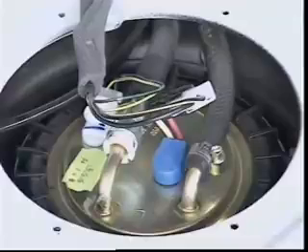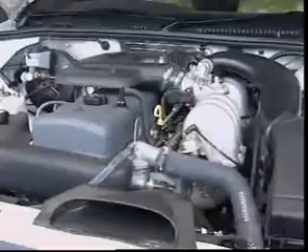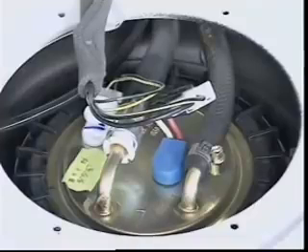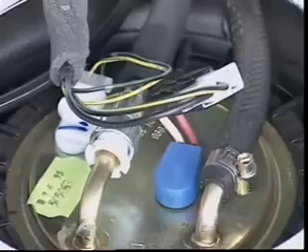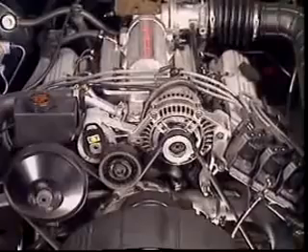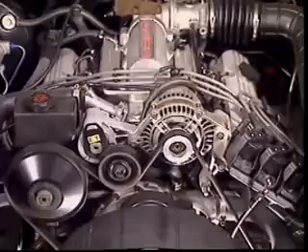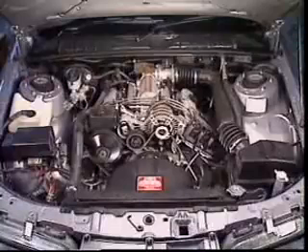The ECU can control the fuel pump. For safety reasons, when the ignition is turned on and the engine is stationary, the fuel pump operates for a few seconds only, enough to prime the engine for starting. It starts again during cranking and when the engine is running above a specified minimum number of revolutions per minute.